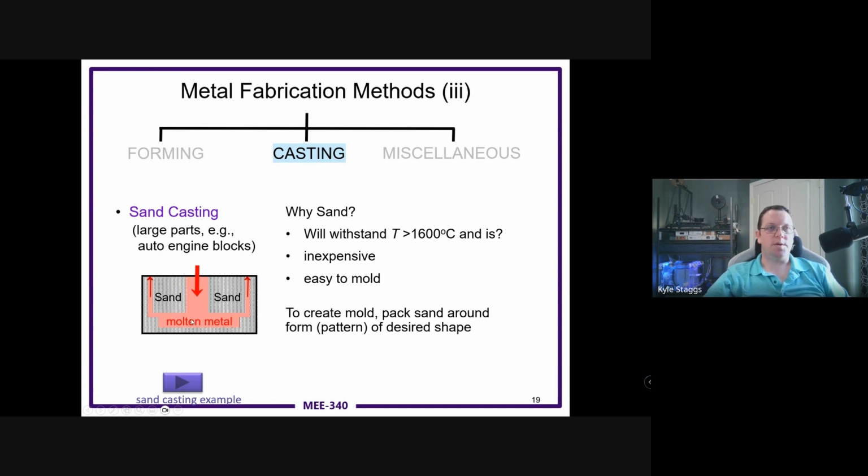So you have the molten material coming in, and you have air escape paths coming out. You'll have different things typically referred to as sprues, which will be material that you may shave off at the end when you do final machining work. But you get the majority of the geometry of the thing, and you only have to do some final machining work, which saves you significant time and cost.